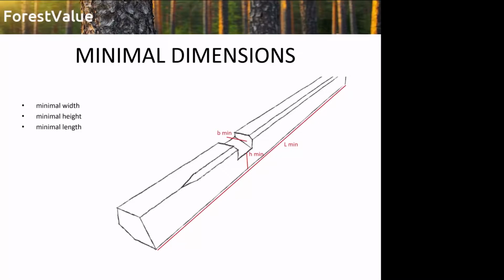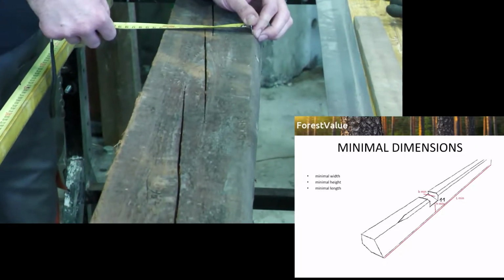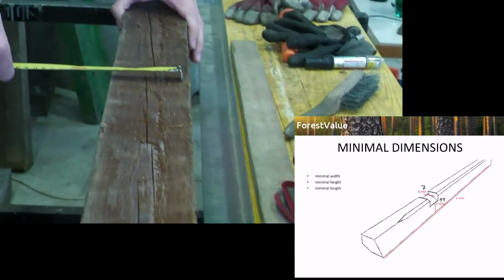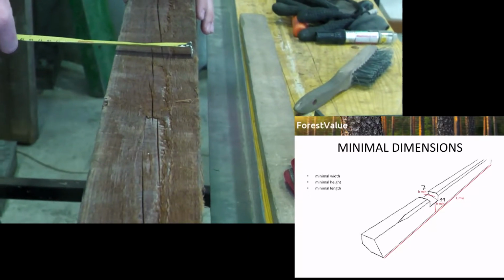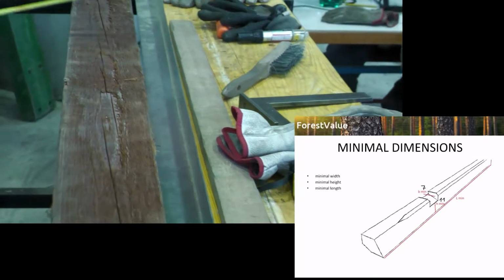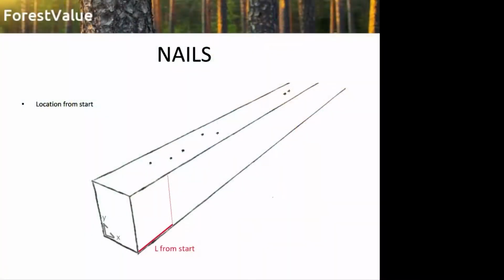When dealing with reclaimed timber, we often have parts with a reduced cross section due to notches, rot, and similar abnormalities. The ends might also not always be cut perpendicular. That's why we also measure the minimal dimensions that represent the longest piece of timber you can get with an unchanging cross-section. We also took into account the reduction due to planing.